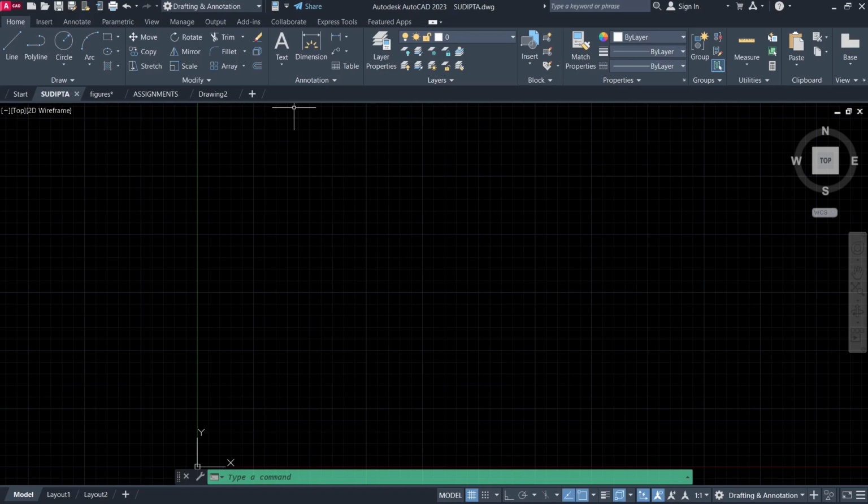Below the file tab, here we will get the black drawing window. It is our working area. We are getting a graph behind. We can switch off this graph, it is not required, from the status toggle bar which is at the bottom of the interface.